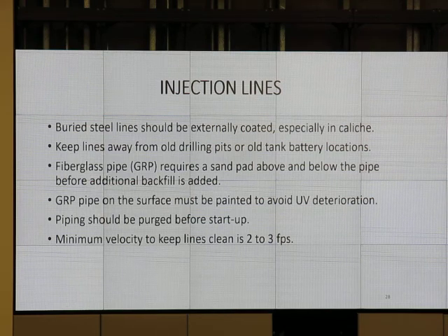Piping has to be purged before you start it up. You'll leave piping out on the ground. It needs to be purged. It needs to have water run through it, air, whatever, to get all the rattlesnakes, welder's rags, hats, fingers, whatever might have been left in that pipe.